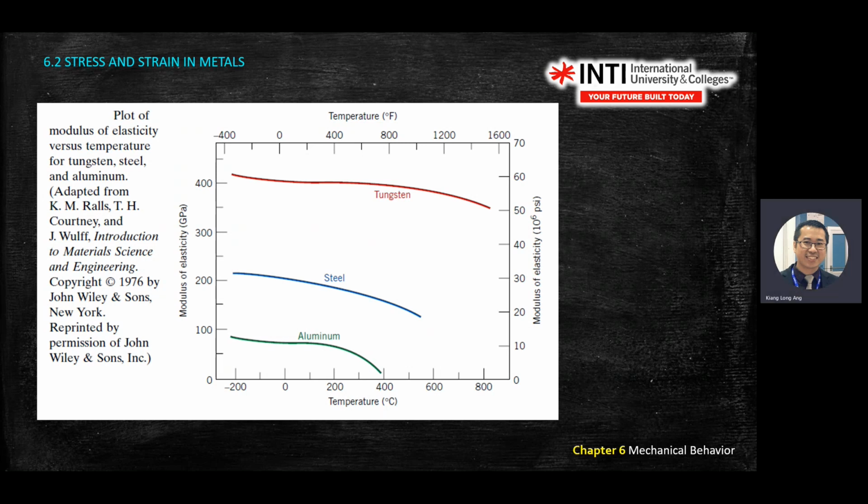Same with the top and bottom. This one is Celsius at the bottom, top is Fahrenheit. In assessment, sometimes you see two Celsius axes, top and bottom. The purpose is to let you draw a vertical line. You draw from the top and bottom, then you get the intersection, the exact point. You'll see that again when you look at phase tables in chapter 7.